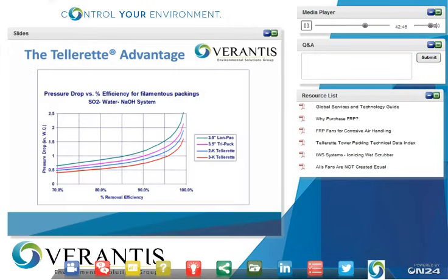And then the last slide I have up here, I put up because it represents a comparison of pressure drop and efficiency. Most curves that you're going to see for packings out in the marketplace, they'll show you efficiency versus gas rate. They'll show you pressure drop versus gas rate, but you won't see the comparative differences, because the two critical parameters, again, for design of a packed tower are you want low pressure drop, which equates to low energy usage, and you want high efficiency in a small contact zone.